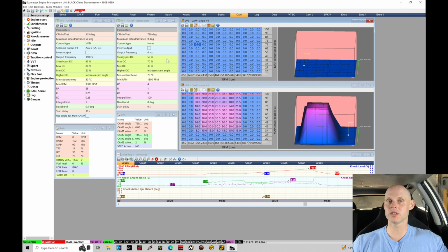Now we have a whole bunch of things to talk about in terms of setting up our VTEC and tuning out our VTEC specific tables. So let's go in and expose where we can find those here in our calibration file and talk about what we need to do in order to set this into VTEC engagement at a low RPM so that we can lock in and calibrate and tune everything here on our Mainline chassis dyno. So let's go in and take a look at our calibration.